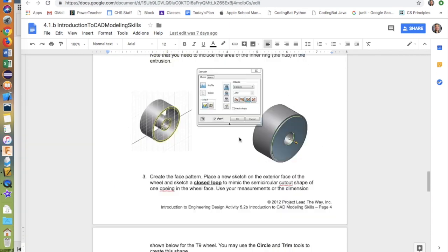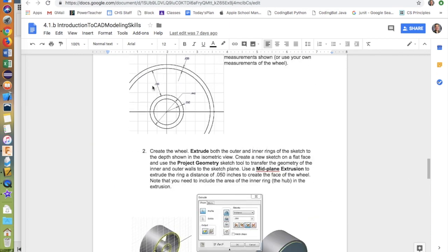part in the middle. Now this one, they want us to use offsets for the different parts rather than giving us diameters for each of the different parts. If we tried using diameters, the distance between these different walls will not match because this is a radial distance. So if we want to do diameters, we'd have to double these different numbers. So we'd have to add 0.35 on one side, 0.35 on another side to the 0.44. So instead of doing that, we're going to use offsets, or we're going to dimension the distance between different circles.